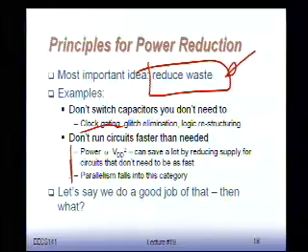It sounds good. I say, well, gee, I can clock this thing at 2 gigahertz. If, however, your application only requires 500 megahertz, you're wasting, right? So make your circuit just fast enough. Being too fast, nobody is going to give you a bonus for that. It doesn't matter if it's video compression or a video application. If you meet the video rate, you're fine, right?